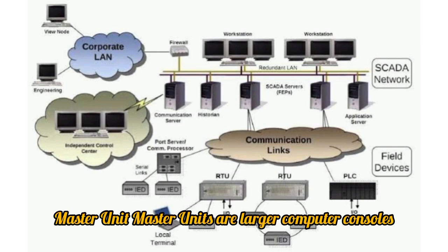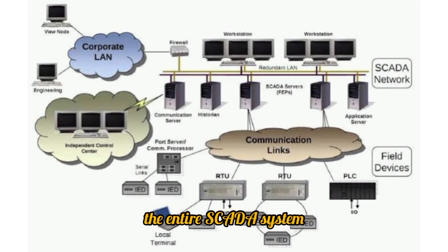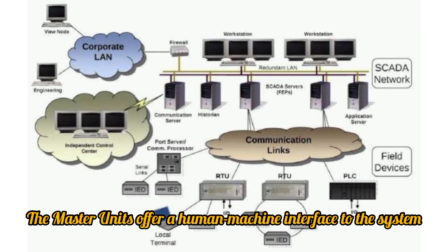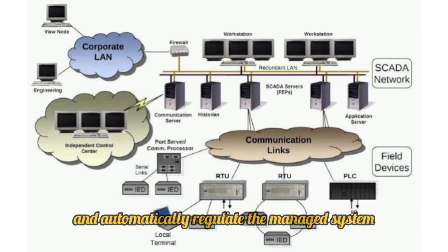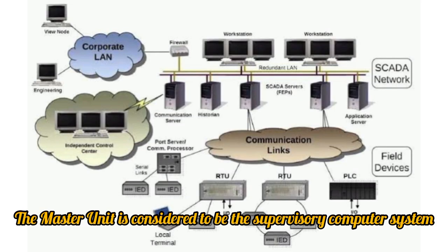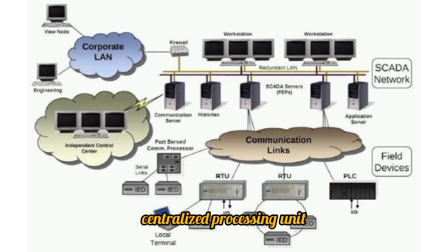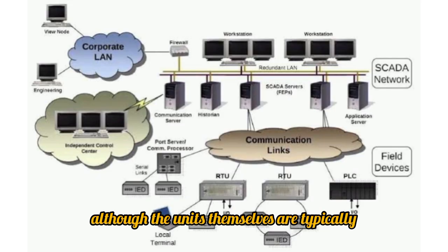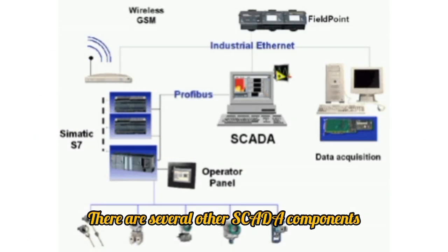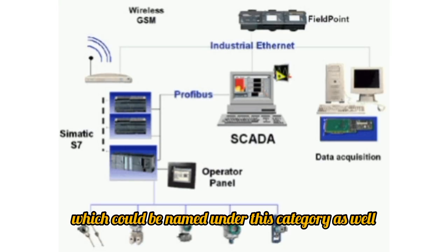Master unit. Master units are larger computer consoles that act as the central processing hub for the entire SCADA system. The master units offer a human-machine interface to the system and automatically regulate the managed system based on the response of input created by sensors. The master unit is considered to be the supervisory computer system because it serves as the SCADA system's centralized processing unit. Although the units themselves are typically larger computer consoles, there are several other SCADA components, such as software programs and HMIs, which could be named under this category as well.